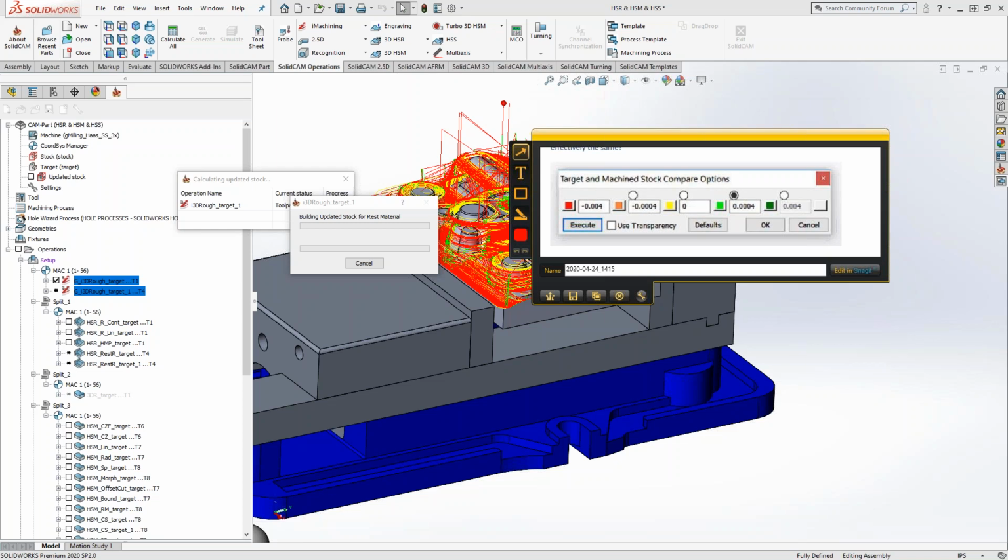And then when he gets to the actual shop and sees what size of stock he has, I would say you can program for whatever size of stock you imagine you're going to use, because a lot of our toolpaths now are stock recognition. So when you do find out the size of your stock, you can change your box definition, or if it's a 3D model, remember that 3D models are associative, so you can change the 3D model to represent the true size of the stock, save and recalculate, synchronize, whatever you're going to do, and then your stock recognition toolpaths will automatically update themselves. So you can always adjust the stock before you G-code the toolpath.